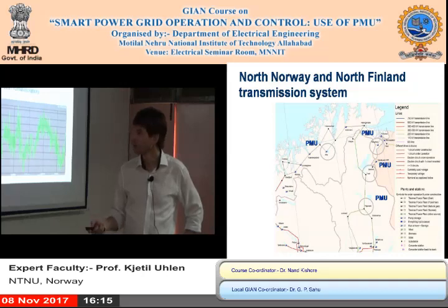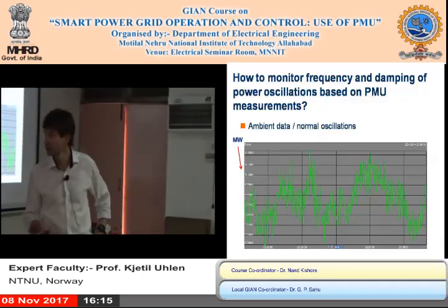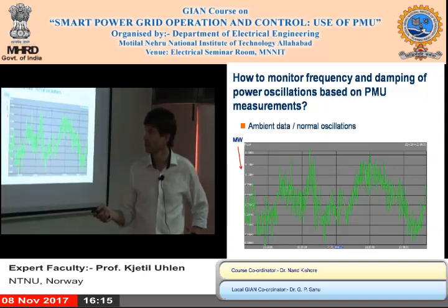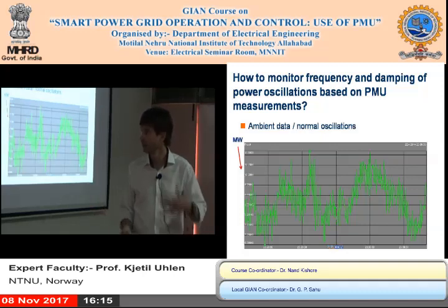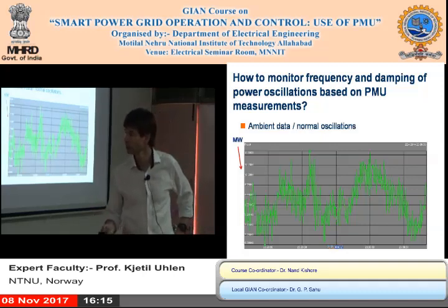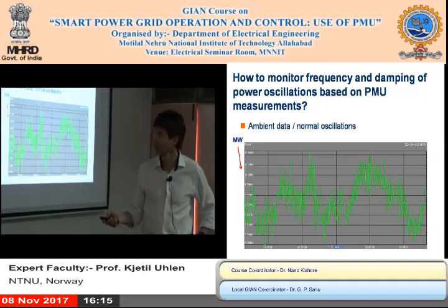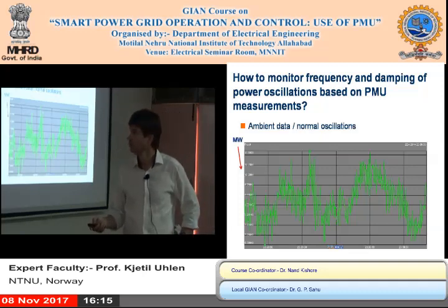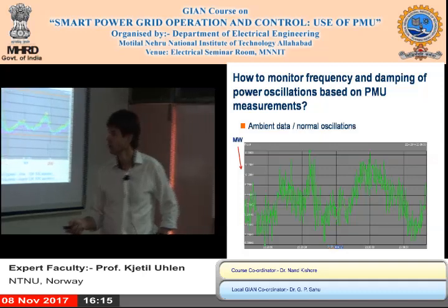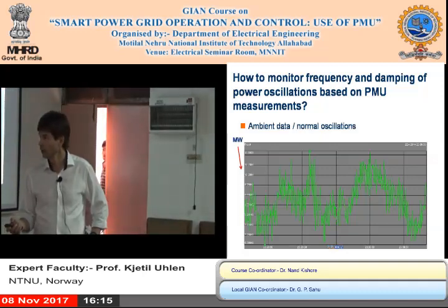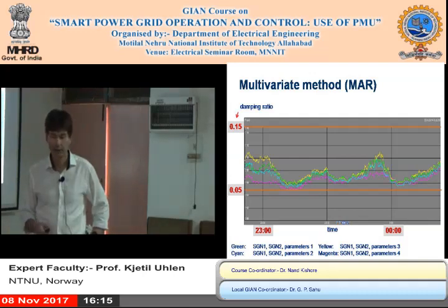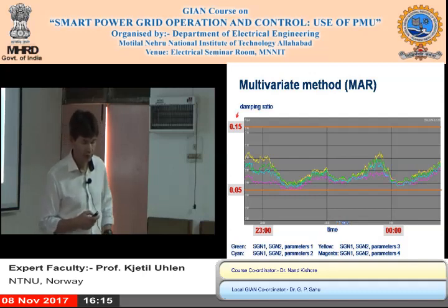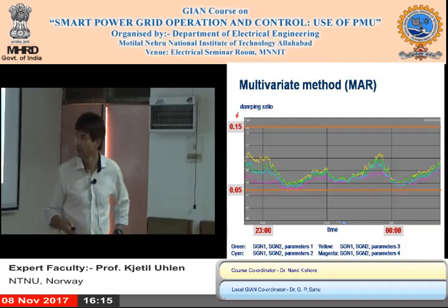So the approach by our Finnish colleagues is to try and monitor frequency and damping of the power oscillations based on ambient data. That means the normal oscillations that are inherent all the time, but hopefully sufficiently damped. The colleagues, Janne Seppinen and Jukka Turunen, who are the two persons who have made most publications in this area, have looked into several methods.